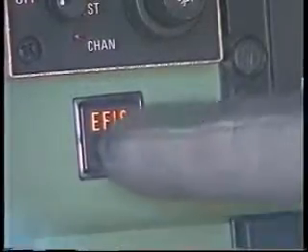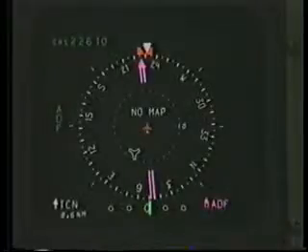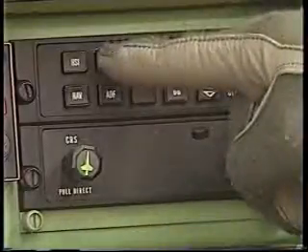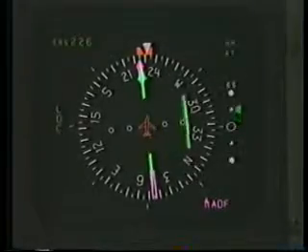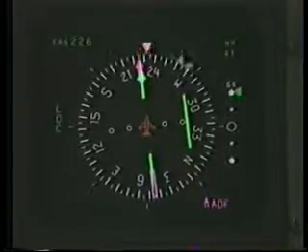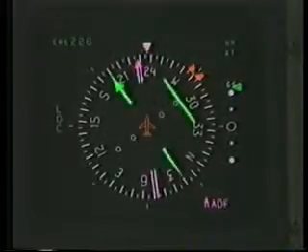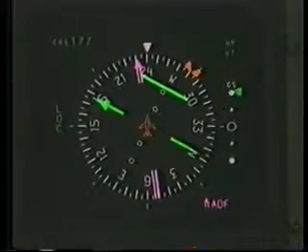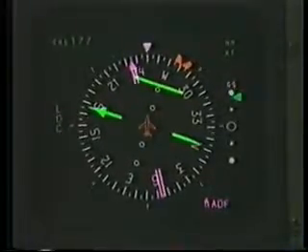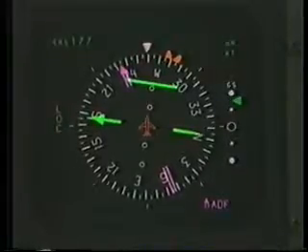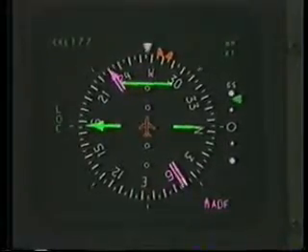Now for the EFIS swap. The screens simply swap over, so press it again for the EHSI. There can't be a proper map display with ADF, so press nav map again for the normal presentation. Now to select the localizer. Notice the glide slope scale, and that the to/from has disappeared. Turn more than 105 degrees from the selected course, and the glide slope disappears.